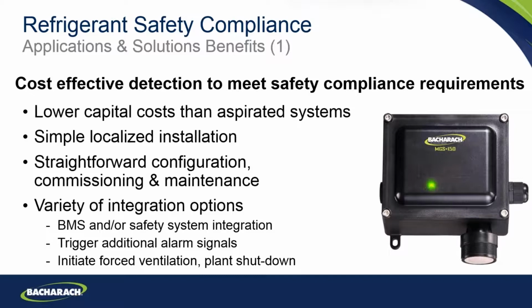So if we're looking at safety compliance, really it becomes a case of cost-effective detection being put in place to meet those compliance requirements. This typically tends to use diffusion-type sensors with semiconductor sensors or electrochemical sensors in them, because this does give a lower capital cost for installation than an aspirated system using an infrared sensor would offer. It means there is very simple localized installation. There is very straightforward configuration, commissioning and maintenance, and depending on the particular instrument chosen, there's a variety of integration options into building management systems or safety systems.